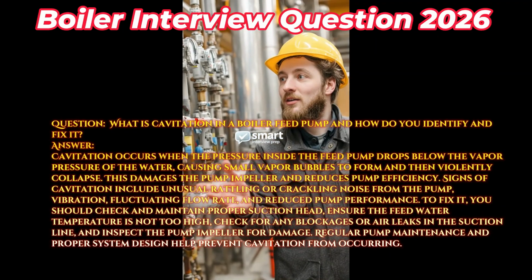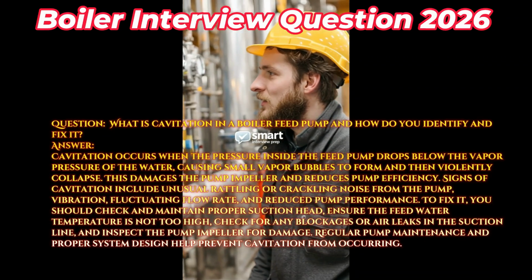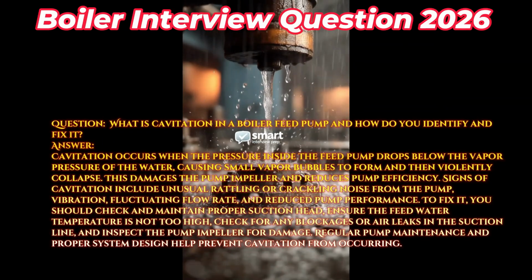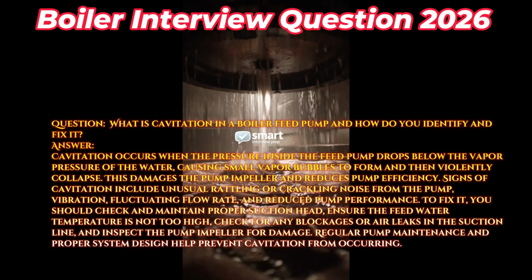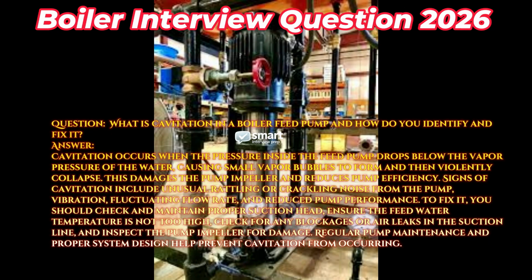To fix it, you should check and maintain proper suction head. Ensure the feed water temperature is not too high, check for any blockages or air leaks in the suction line, and inspect the pump impeller for damage. Regular pump maintenance and proper system design help prevent cavitation from occurring.